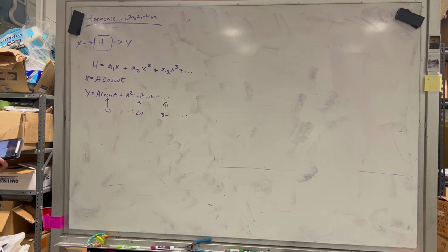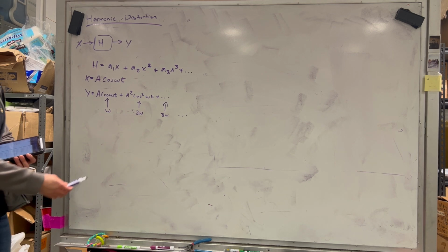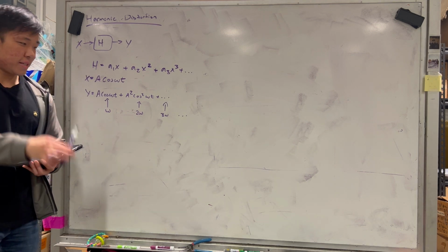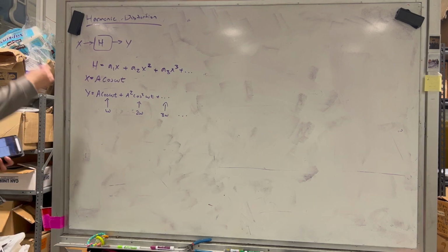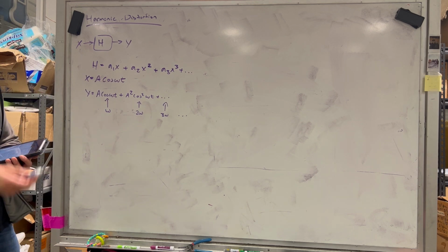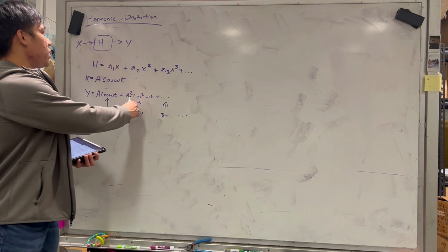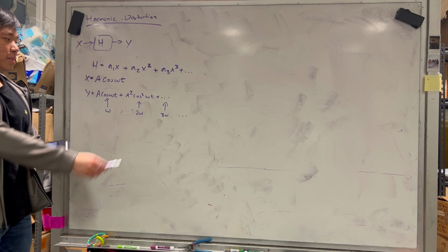Particularly with your oscillator, if you took the FFT of it, you should have seen peaks at 4 meg, at 8 meg, at 12 meg, at 16, and so on. The strength at each of those harmonics decreases, and that's just because of the power reduction formula.